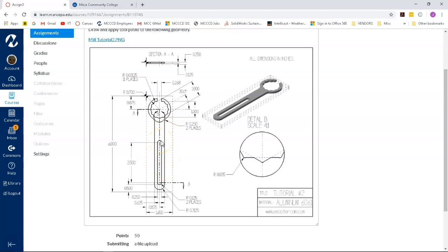This is called out as aluminum, but I really wouldn't make a wrench out of aluminum. I mean, one-time use maybe. And especially with the thin cross sections, this would be a good one to put into SolidWorks and do a little simulation on how fast it will fracture through that thin cross section, where even without the stress riser of a 0.35 radius in the corner, I think it's still prone to fail.